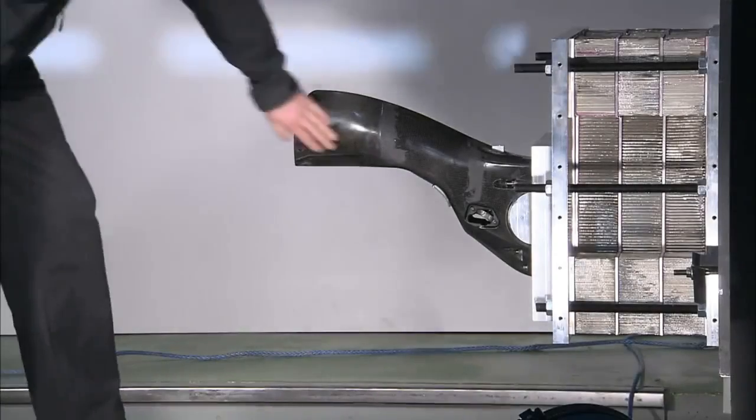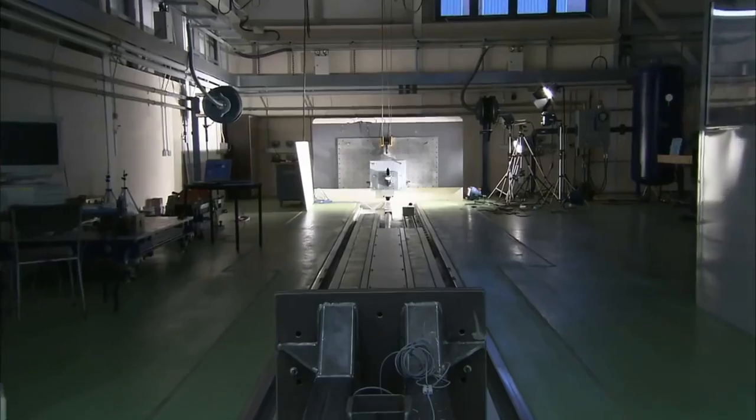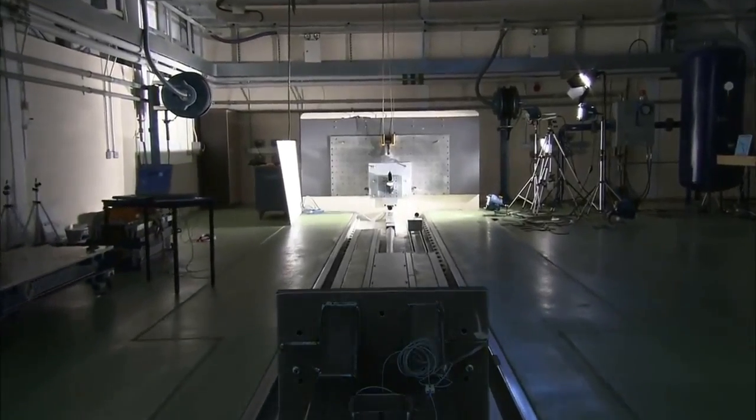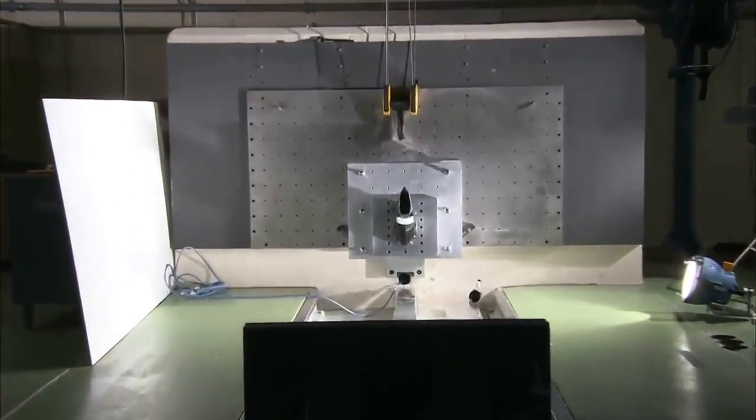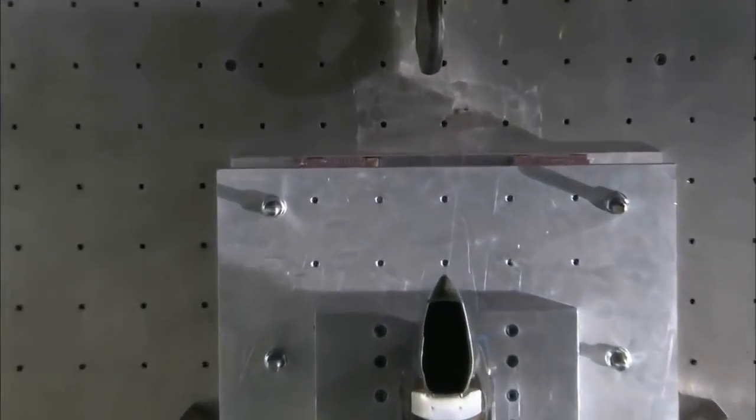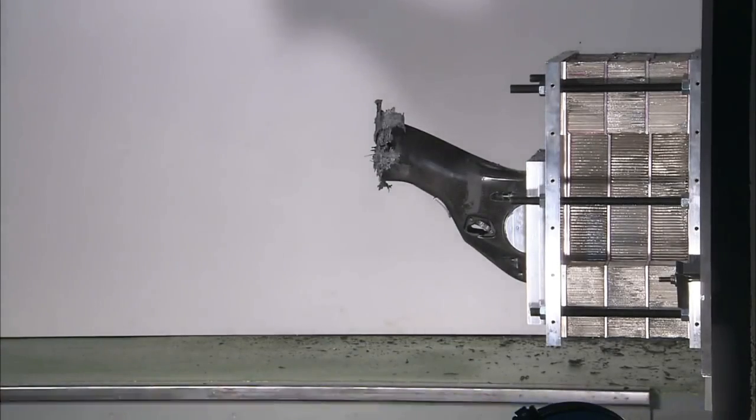So here is our subject. Still warm coming out of the autoclave, I see. Now let's drive a high-speed ram into it and see what happens. Wow, that was a bit dramatic. Looking at it in slow motion, it's very clear there's a lot going on. And it's also pretty clear that composites don't fail in compression at any singular point. They fail in a somewhat uniform manner.